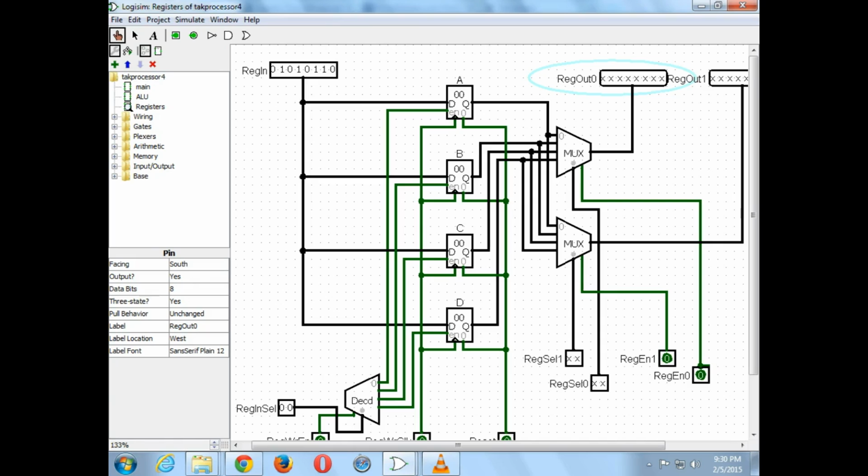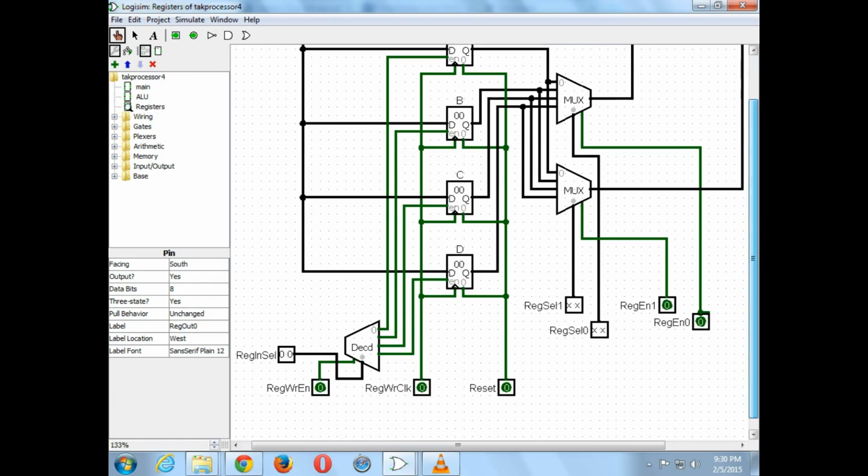if we were to say register select, I think, well, if you can scroll down right here. Yeah, so if we were basically saying that the decoder is not going to turn any of those on, then it wouldn't change any of the registers. But it really has nothing to do with this part. All of these circuits are still static. They are not changing anything. The only one that matters is the clock line, because the low to high transition only happens in an instant. And then after that, we can change the input to the D port. It's not going to do anything anymore.